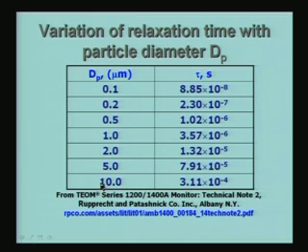These are very large particles and these are relatively smaller particles, and this is the kind of particle we talked about when we were talking about the diesel engine. So, you see that the relaxation time is very small, about 10 nanoseconds here, and then progressively here it is about 1/10 of a millisecond. For very large particles, this relaxation time has something to do with the isokinetic sampling. We require that Stokes parameter to be less than 0.01, and this relaxation time goes into that formula.